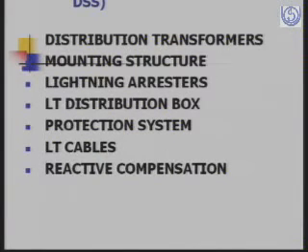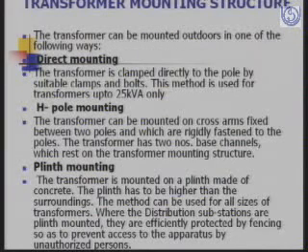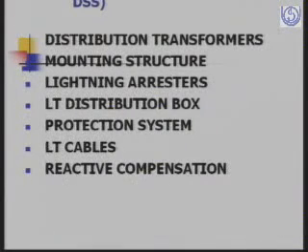So the distribution transformers are of various ratings, as we earlier also said. The distribution transformers can vary in ratings from 5 kVA to 1000 kVA, and usually smaller kVA transformers should be preferred so that they can be placed nearer to the load center and the losses are less. And we'll come to details of distribution transformers when we come to transformers.